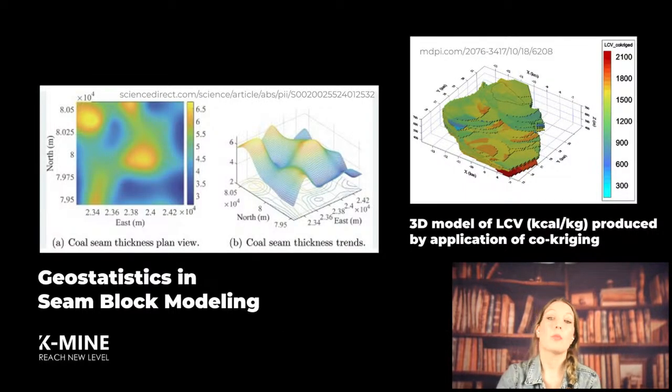Over the past decades, there have been several key advancements in seam modeling, including the use of seismic data to confirm geological continuity between boreholes, innovations in geophysical logging technologies such as the development of borehole imaging tools, and the adoption of geostatistical methods like inverse distance weighting interpolation, nearest neighbor interpolation, modified Shepard interpolation, and various kriging methods such as ordinary, simple, universal, disjunctive, cokriging, and indicator kriging. Also, enhancements in surface modeling algorithms allow for quick evaluation of alternative geological interpretations.